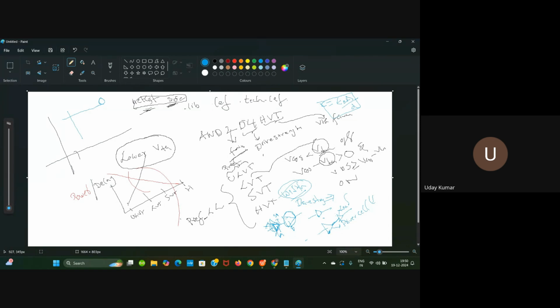Similarly, this is the naming convention of the standard cell. Sometimes if you want to reduce the delay, you'll have the same convention, but you'll just change here. You'll be able to swap one cell for another cell readily with the same convention, and ULVT will be readily available at the cell level. So we can just swap it whenever required. That's how things work with standard cells.